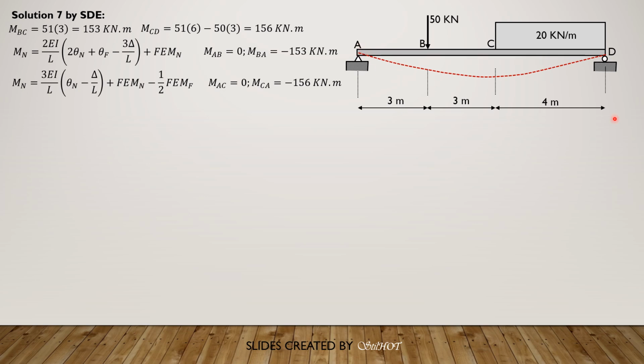So we consider moment AD first. Then because we anticipate that there's no problem with this concentrated load, we can write the fixed end moment formula only for this loading, which is at a certain segment only of the beam. So we consider a strip. The P here is 20 dx, the thickness is dx, and because the height is 20 kilonewton per meter, so it is 20 dx the P. So we will call this x, and this is 4 minus x.